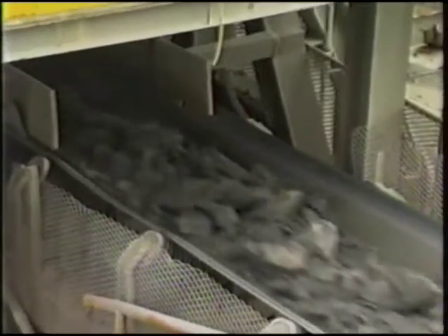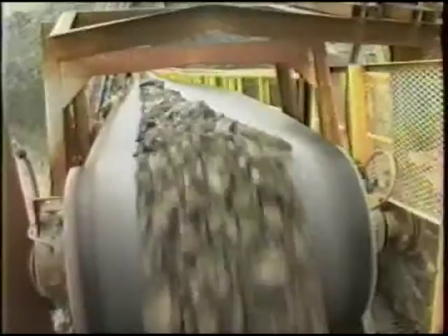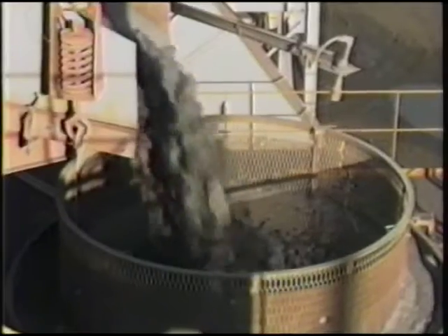The purpose of the primary crusher is to reduce the shot rock to a size that is easily and safely transported upon belt conveyors to the secondary crushing and screening stage. Before the stone reaches the secondary crusher, it is fed onto a vibrating screen, often referred to as a scalping screen. The function of this screen is to separate large pieces from ones that are typically smaller than 2.5 inches, and then route the larger pieces through the secondary crusher. All material larger than 2.5 inches is either scalped off as riprap or is fed to the secondary crusher for further size reduction.